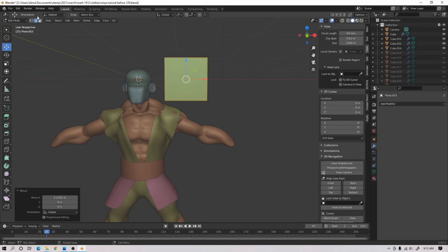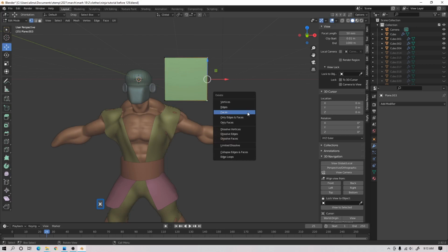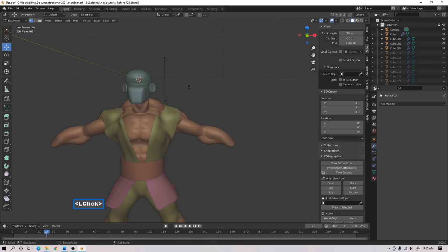We're going to go to the upper left, go to Vertex, select the top vertex, hold Shift, select the bottom vertex, press X, and this brings up our delete menu. We're going to select vertices. We just have these 2 vertices right here. Be aware that we started to manipulate the plane after we came into edit mode, all right? And our vertices are here. Our origin point is there.